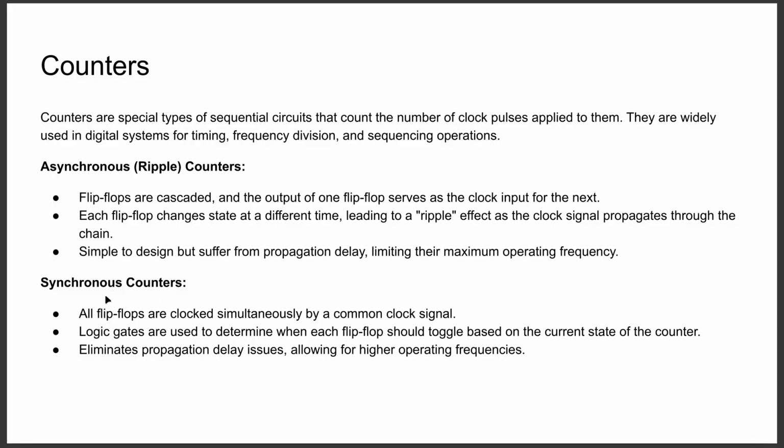Synchronous counters. All flip-flops are clocked simultaneously by a common clock signal. Logic gates are used to determine when each flip-flop should toggle based on the current state of the counter. It eliminates propagation delay issues, allowing for higher operating frequencies.